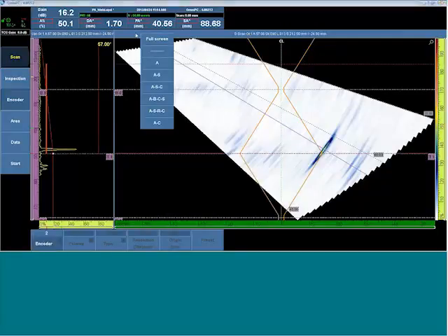So whenever we talk about setting up the scan menu, we're talking about configuring the scan axes, always in blue, and it is the long axes of the B scan and C scan. So our area from the scan submenu is the start and stop position.